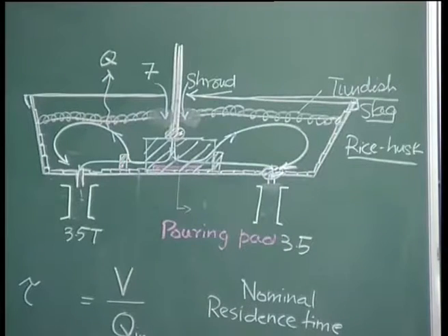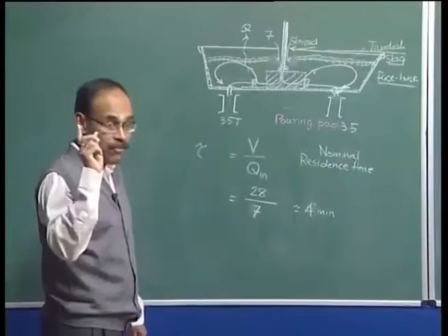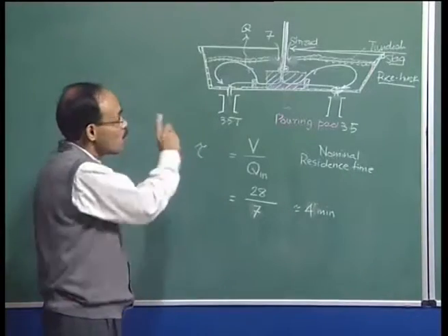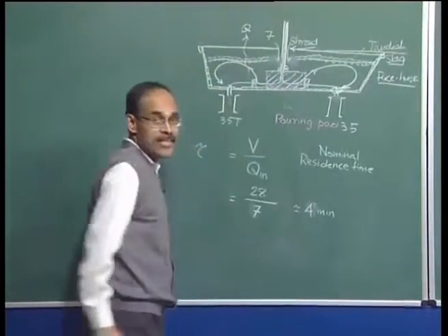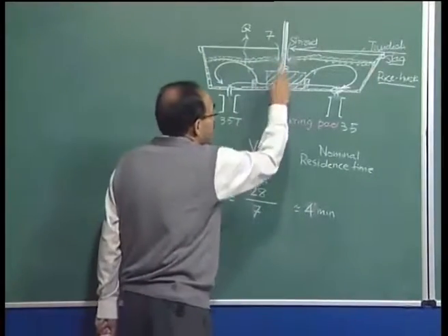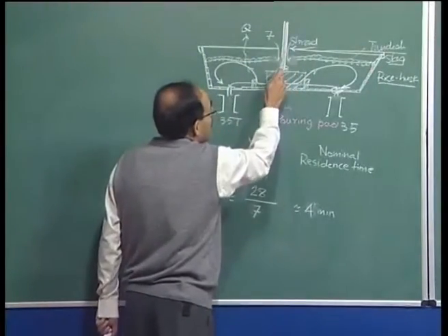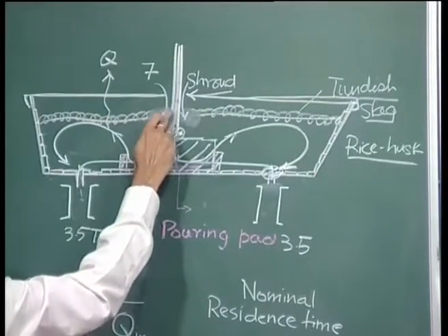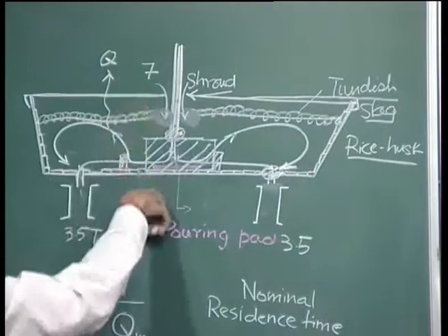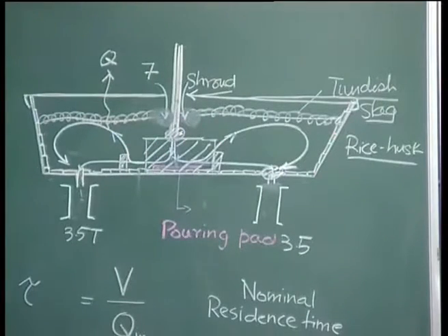We are always worried about reoxidation in the ladle and in the tundish, and reoxidation, as I have categorically mentioned, spoils the quality of the steel. So, the slag layer need not be broken at any stage, and it is here, immediately above the impinging jet from the ladle, that we have a possibility of breaking the slag layer, whereby atmospheric oxygen and nitrogen can go into the melt.